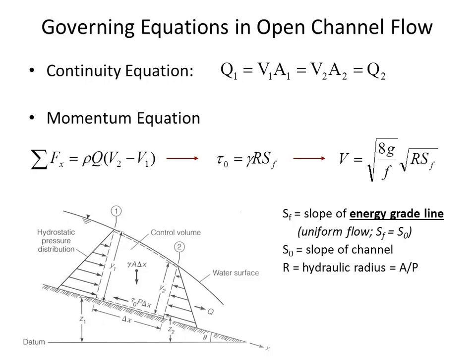Since we've got a changing water depth, since Y1 is deeper than Y2, that tells us we don't have uniform flow. So this is non-uniform. And we have to ask ourselves, why is it non-uniform? What is it about this that could be drawing down the depth? Any thoughts on what could cause non-uniform flow like this?